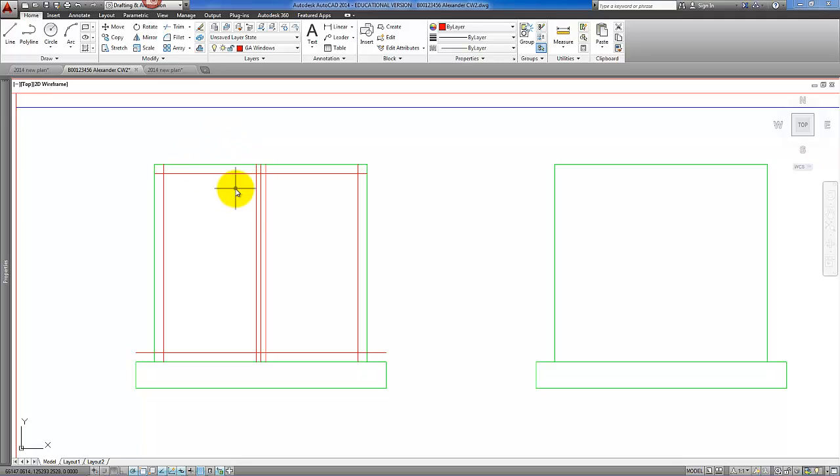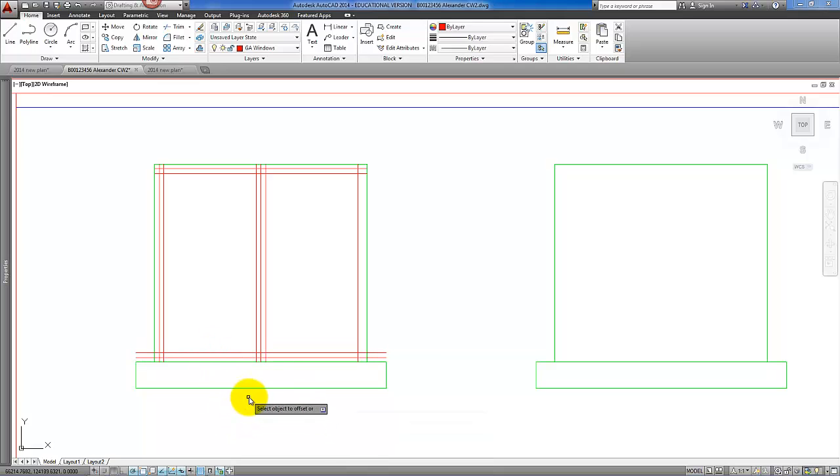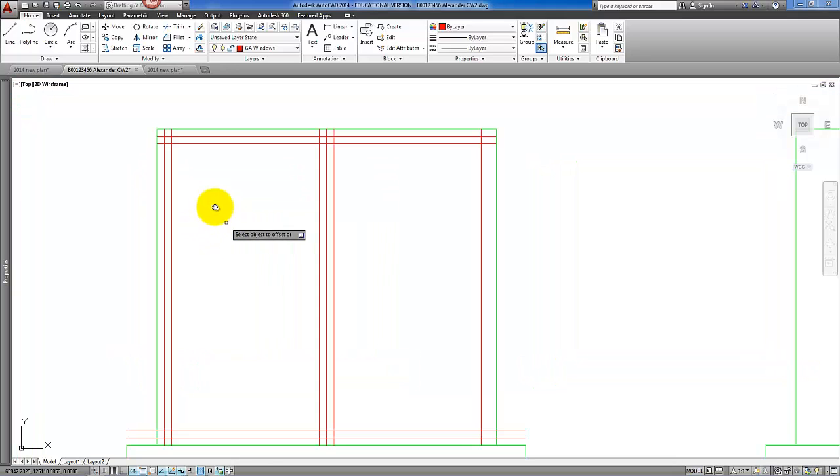And actually on this side it will be a little bit different. It will, because it's an opening light, the frame will actually be overlapped by the opening light. So let's offset again by 25, like so. And really that gives us the basis of where the opening light would go. So it's closer to the reveal and the head and also the sill.